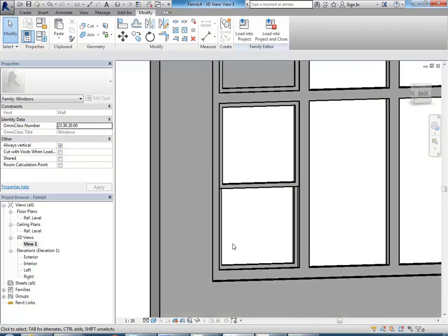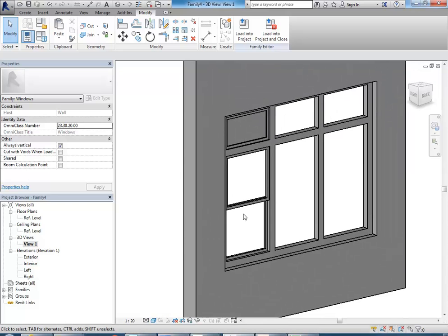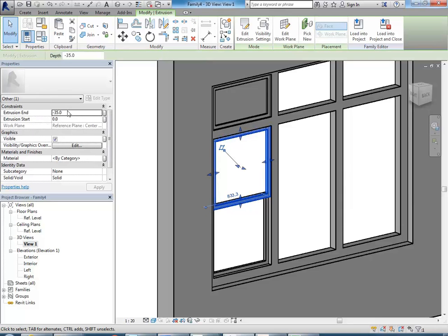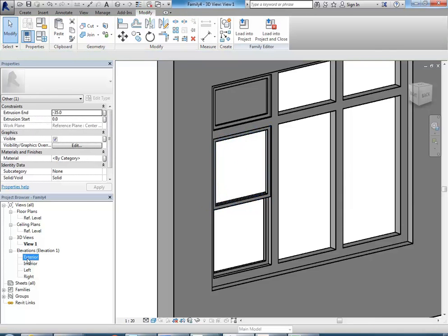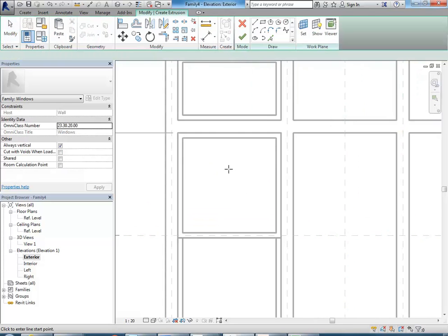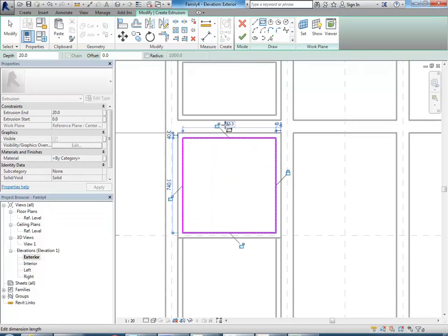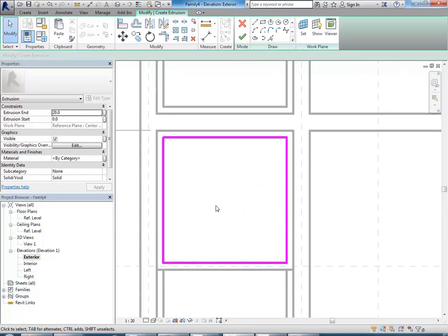Oh yeah, sure. Okay, so now I put the glass in. The glass should be easy now. So again, remember this one's going to minus 35. So if I go to the exterior view and make a new extrusion, okay, so doing a bit of mental arithmetic. If it's, well, I'll just type it in so you can see. So it's minus 35.